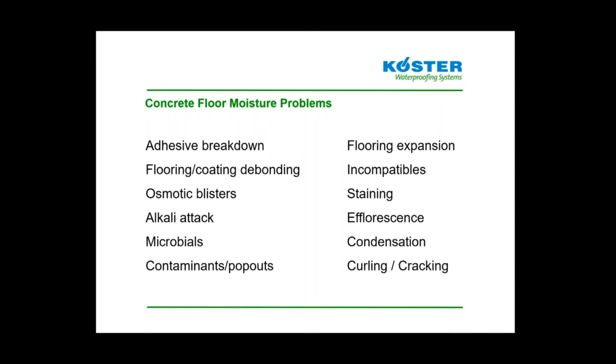So obviously concrete is made with water, and the presence of water in the concrete, and potentially from exterior sources such as groundwater or topical water, can contribute to a wide range of problems with floor covering systems and flooring systems in general. Most commonly, what we're seeing is adhesive breakdown due to that high moisture and high pH, debonding of flooring systems or coating systems, as well as osmotic blistering.